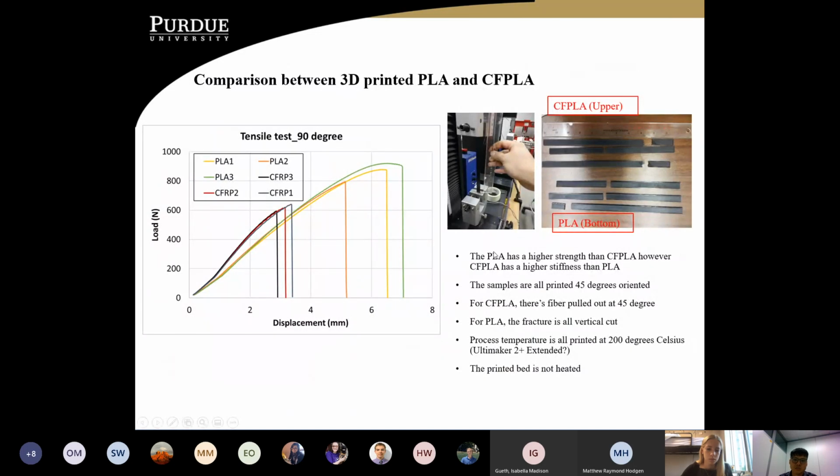So over here, you can pay attention. Now I just go over with the stress-strain curve, right? This is just a common stress-strain curve. Nothing changed. I just put load instead of stress, displacement instead of strain. And then we can see over here the CFPOA, a CFRP with a different acronym. POA is the same material that the EPICS office is printing. Now you can see this curve over here. Let's compare which is the highest one. These three are the highest, and these three highest are actually the POA. And the three over here are actually the bottom ones, right?